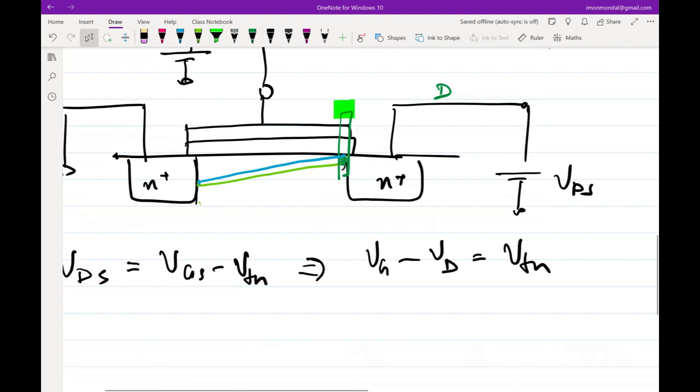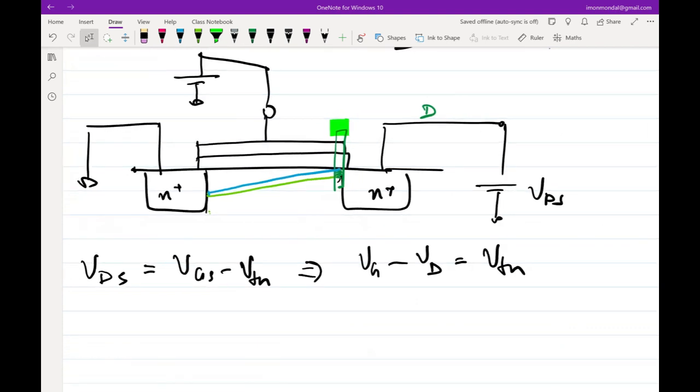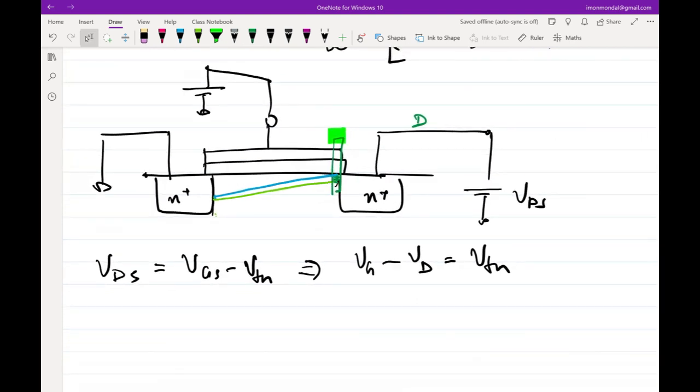The reason is that water flow is purely gravitational. Here it has another aspect to it. The analogy that I gave might make it appear that once we apply VG, if there is no channel, there should not be any current. So I2 should be 0 with that analogy.